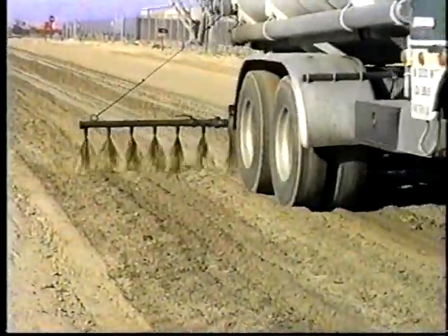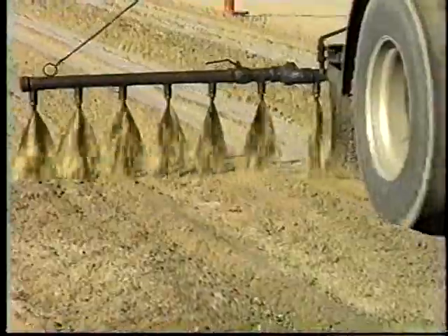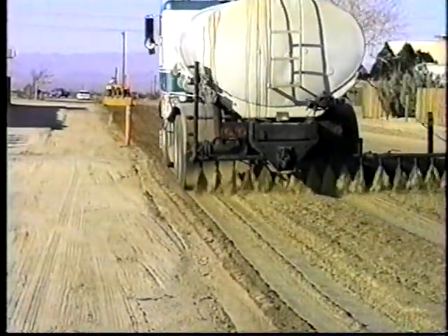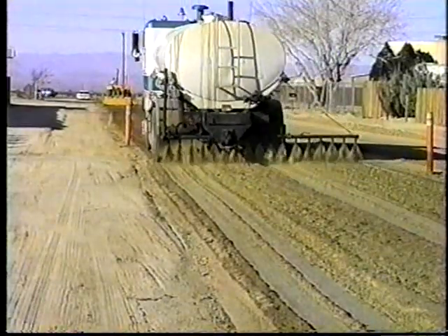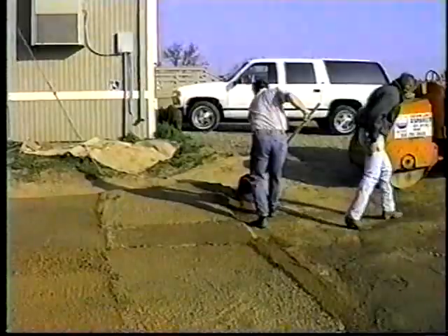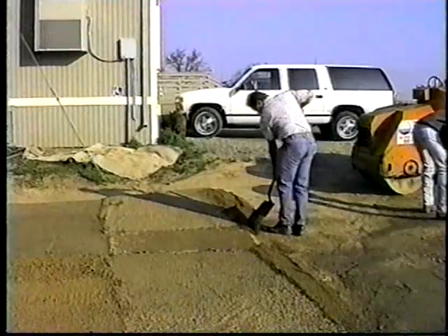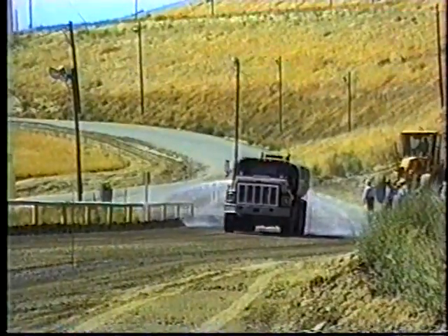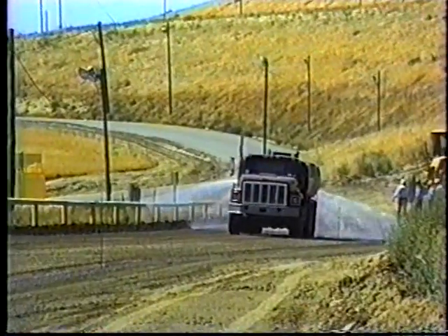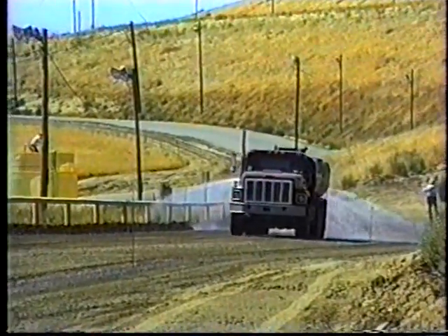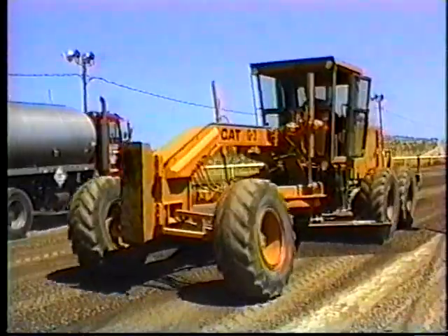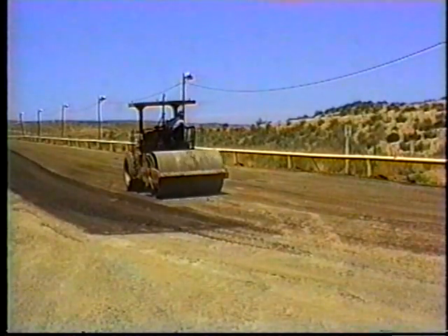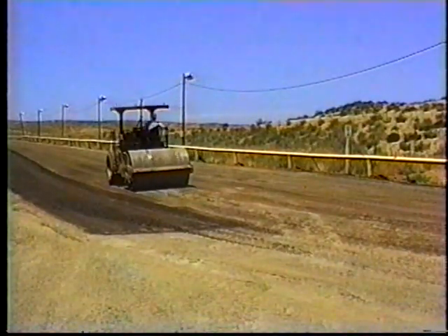In the absence of budgets to run laboratory mix designs or to purchase adequate product to meet pavement stability standards, application rates and construction procedures are often determined by existing local experience or by construction of test sections in preparation for full-scale construction. Similar to pavement applications, aggregate materials must first be brought to an appropriate moisture content before the undiluted road oil emulsion is applied and mixed with the aggregate. Thorough mixing and proper compaction are essential to performance.